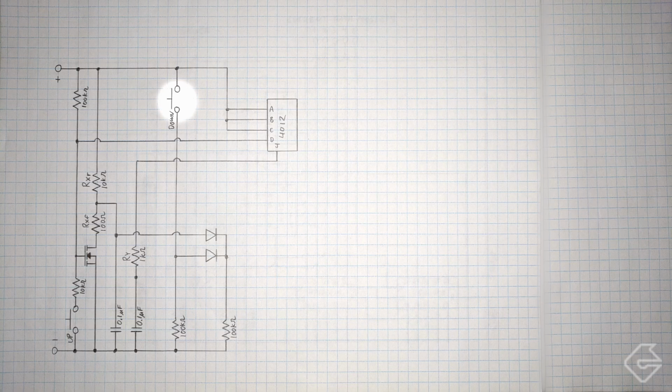And when the down button is here, you'll notice that it's going to these diodes. Now, these diodes were in the first diagram as well. They were in a different position. They weren't actually oriented like this. But the purpose of these diodes is an OR gate. Remember, we had that OR gate right in the beginning of our original circuit. Well, we still need that OR gate, so that's why these diodes are here.